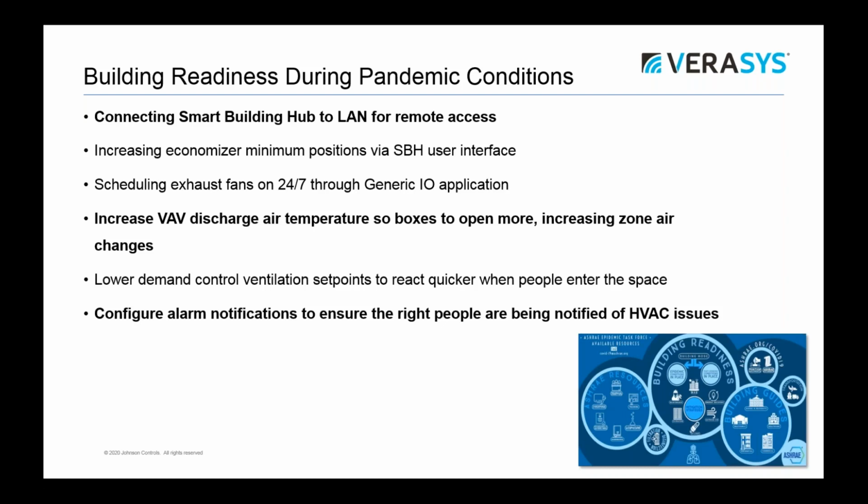Lower demand controlled ventilation set points to act quicker when people enter the space. And then a really important part is being able to configure alarm notifications to ensure that the right people are being notified of these HVAC issues. Even getting alarms remotely from fan status, dirty filter status, those types of things. So Verasys plays really well during this pandemic.